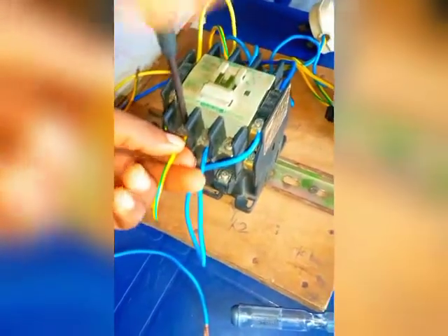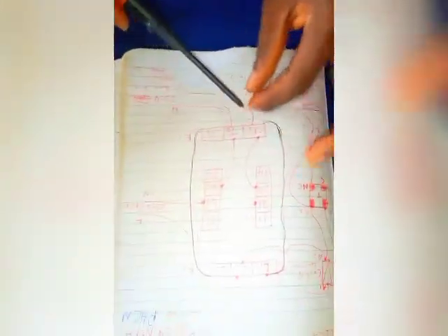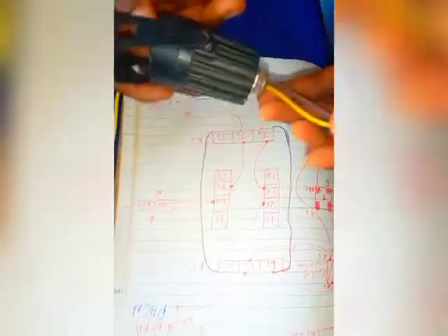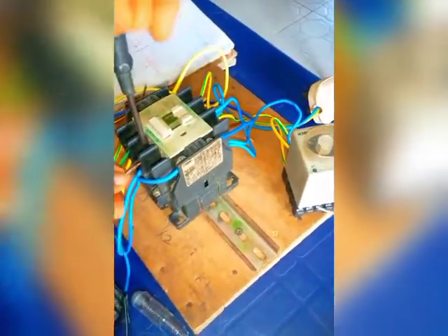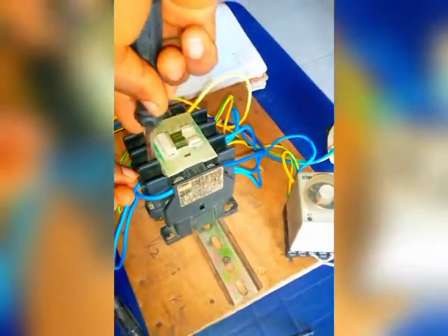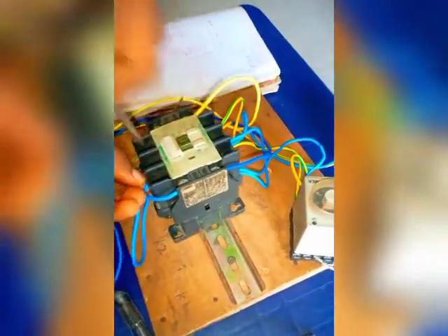Looking at the diagram again, you see that the load to your house comes from T1 and T2. Because we are using this as the load, we connect it to this T1 and T2. So I connect this to T1, which is this place, and I connect this one to T2, which is this place. All right, so now we are done with this connection, and what is remaining now is for us to test.